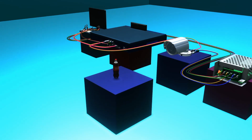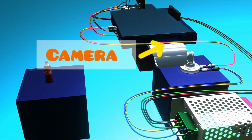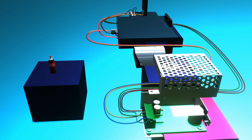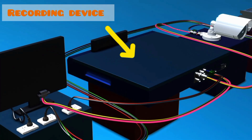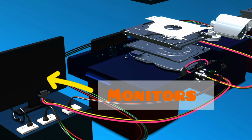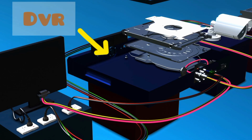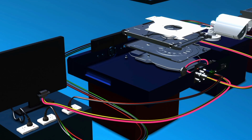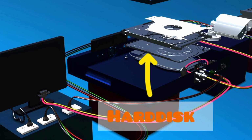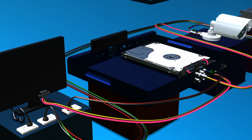To have a complete CCTV system, we must have a camera, a power supply, a recording device, and a monitor. For analog cameras, the recording device is called a digital video recorder, DVR. For IP cameras, the recording device is called a network video recorder, NVR. In this discussion, we will focus on the DVR. Inside the DVR, there is a storage device called a hard disk drive, which stores recorded footage for playback and review.